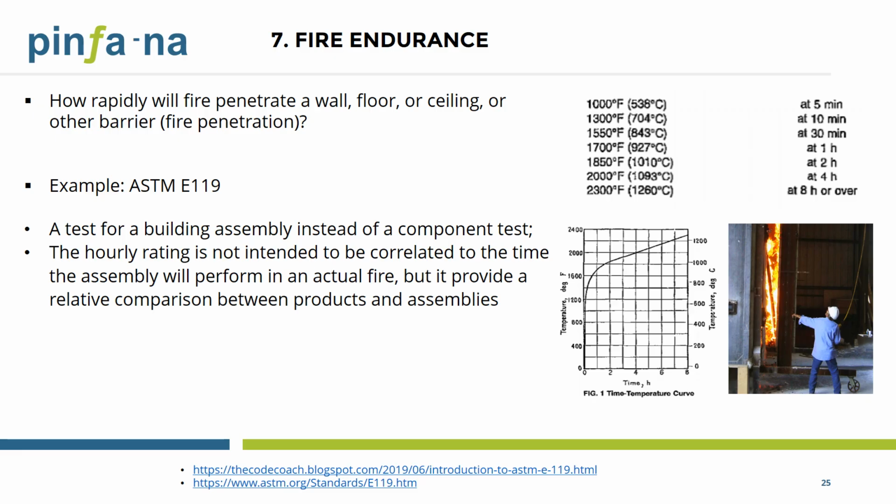The rating is expressed as the hourly duration, matching the time the assembly can be tested up to per the condition of acceptance defined in the standard. A couple of takeaways here. First is a test for a building assembly system instead of a component test.